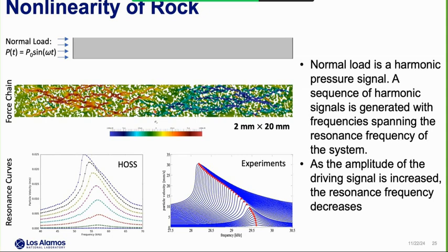We figured out that the main reason that caused that nonlinear response is the interaction between the grains. And by the way, for that microstructure, we have thousands of grains, and during the simulation, they are interacting with each other. We were very happy with these results, and we published the paper a couple of years ago.